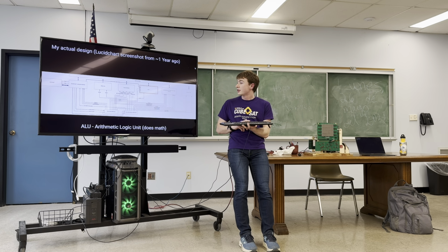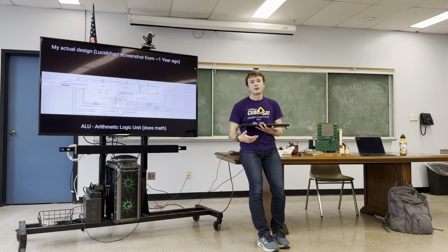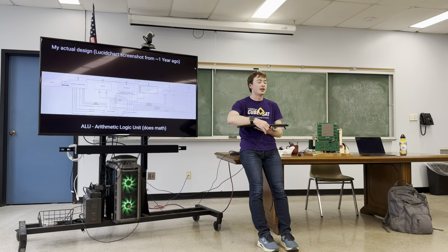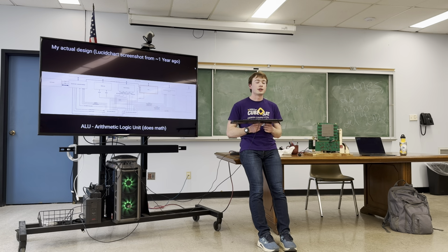This is what's traditionally called the arithmetic and logic unit, and it's for doing math and logic. The one I have is really simple. It can only do addition, like what I showed earlier, and subtraction, but you have to use more operations for the rest. The rest of the operations are just bitwise, like it does an AND with the corresponding bits of two inputs and produces an output from that.